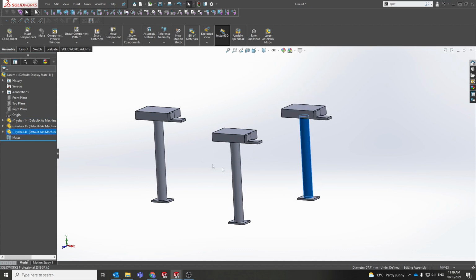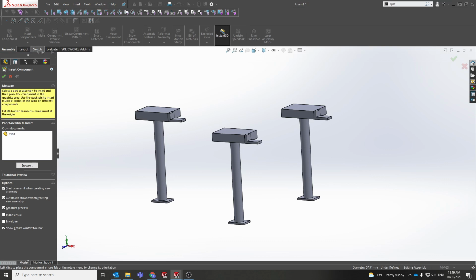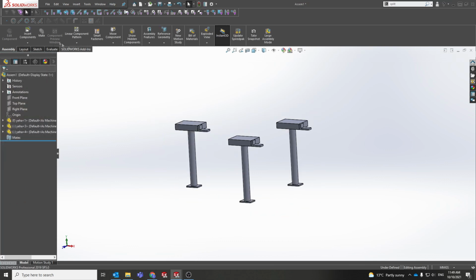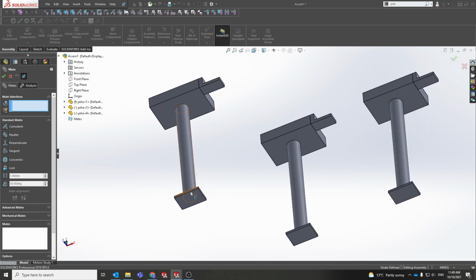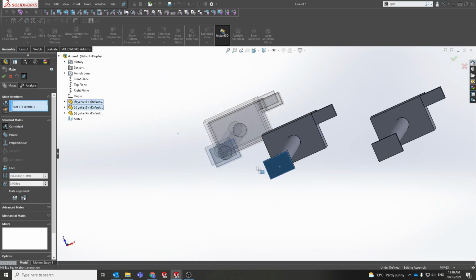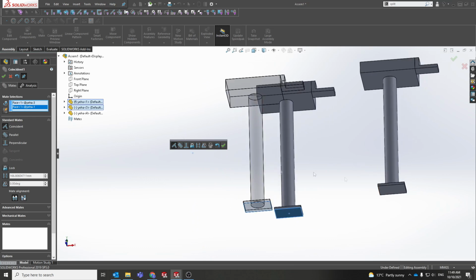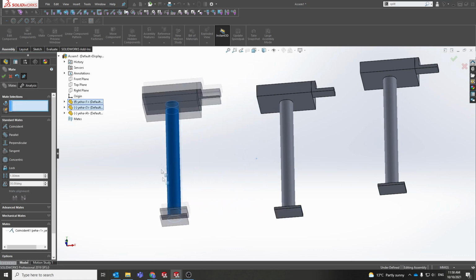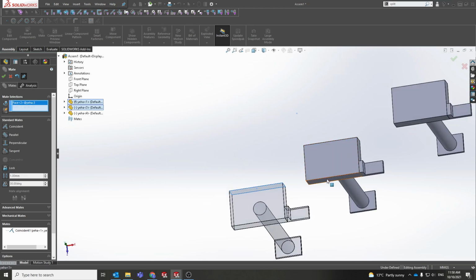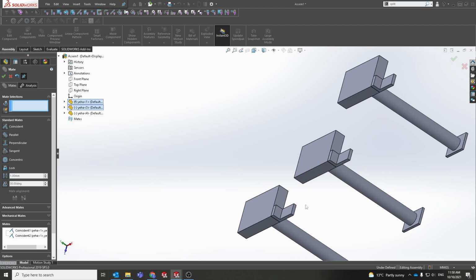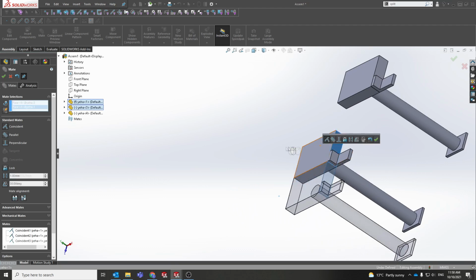Now these things aren't what's called mated in SolidWorks, so that's the term for constraining assembly parts. So if I get out of there, we got to our mate, a little paperclip icon, and this is where the magic happens. So if I want to go this surface with this surface, so I've selected those two things, I can either press enter or I can use the OK button up here. So now it's in those planes, and then I might say, okay, now I want to go this surface and this surface. Okay, or enter I just used, and then same with that. Voila.